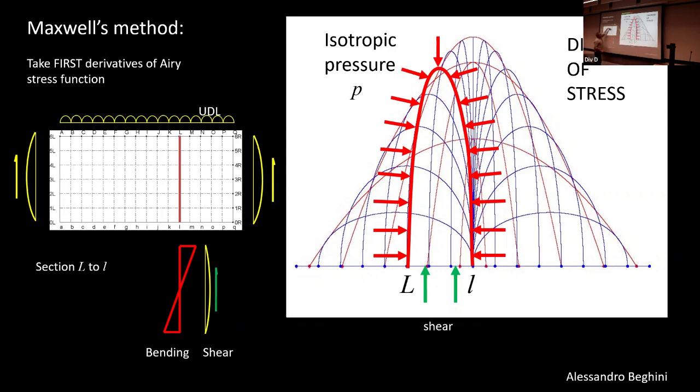Well, there's some shear pressing down, which are those ones pressing down. There's a small shear pressing down. And in fact, if you make this a closed loop, the total force from L to L, these ones add to 0, and it just leaves you the upward component. So that distance accounts for the shear pressing down. It should be the same as that distance there, times the load there. So this contains all the information about the stresses within the beam. And we only took first derivatives.